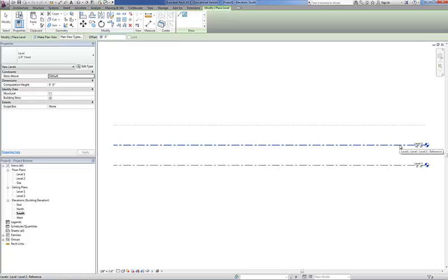And if I hover over these lines, you can see that this preview line, that dashed light blue line, that's going to be where a new level will be created if I were to select this level 2 line. Now, the reason why I wanted to offset at 10 feet is just to show what happens if you hover over that level 2 line, then the dashed blue line preview for the next level is right where level 1 is. And if you're not careful, you could keep selecting level 2 and make new levels on top of levels that you already have. Revit is not going to tell you that you already have a level in that exact same place, because there may be some occasion where you want to have that. We don't want that right now because we're going to have these separate levels established.